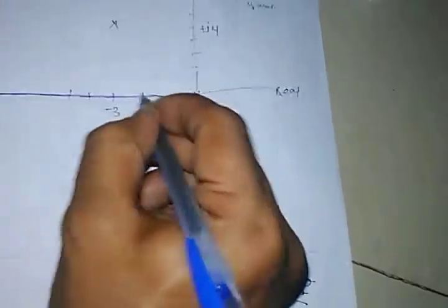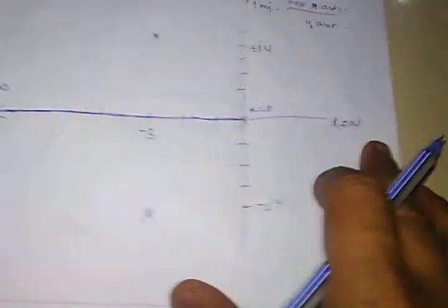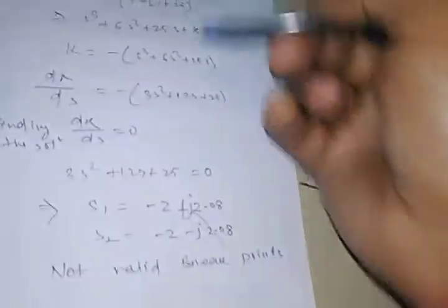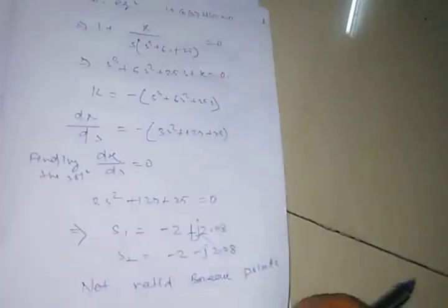It will come out on the real axis. We have to darken the negative real axis, and we will give the arrow and mark here minus infinity, and at this point it is k equals 0. Okay, and there is no breakpoint, only the centroid is there. Point number 5 does not come out. No valid breakpoint. This point is on the root locus but not on the real axis, so it is not a valid breakpoint.